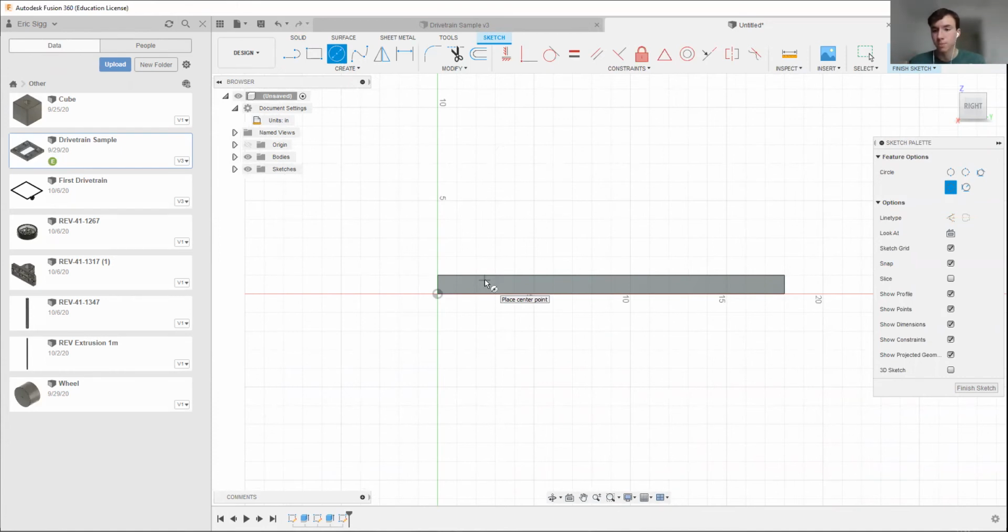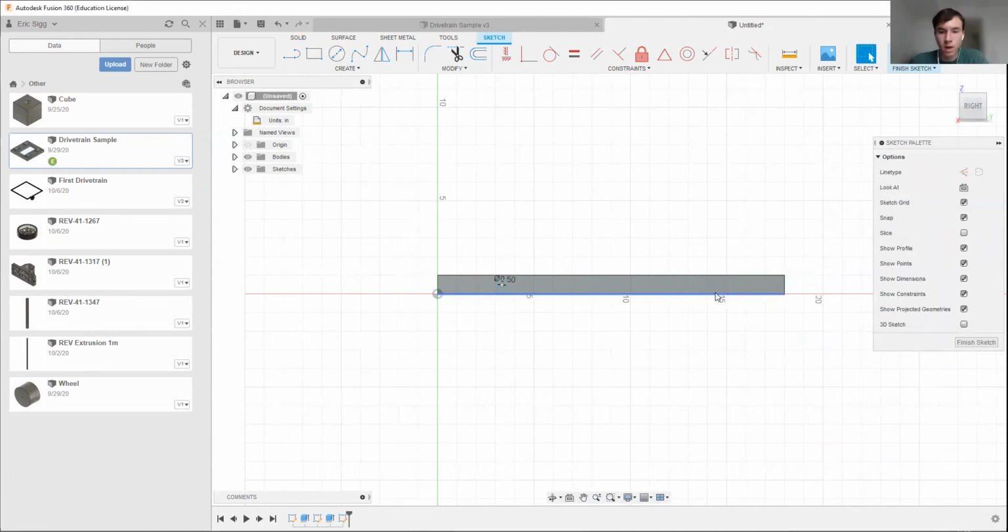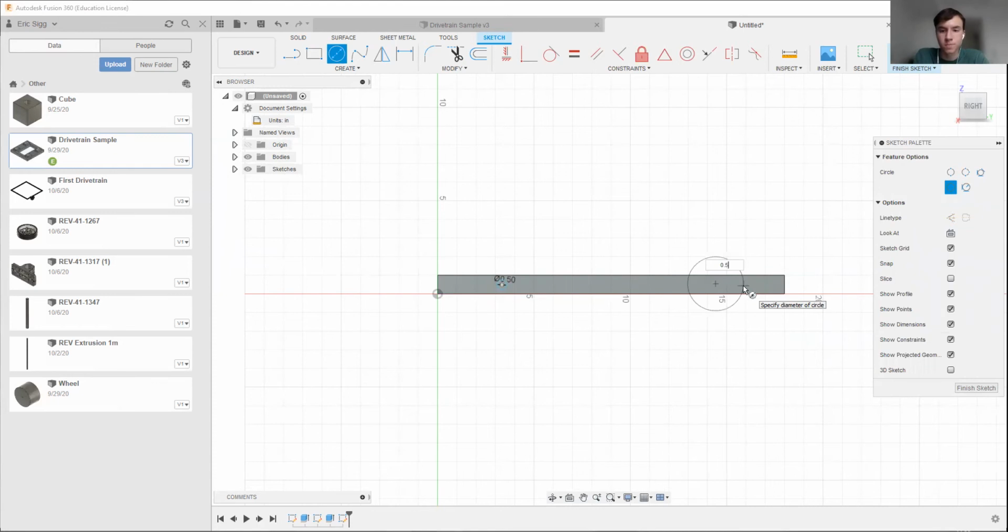this direction. But I can remember that from the math I did earlier, exactly where the wheel wells are, and just do the addition and subtraction to find the right spot. So if I can just place a hole here somewhere, I'll make it 0.5 inches in diameter. Now I'll do that again over here, make it 0.5 inches.